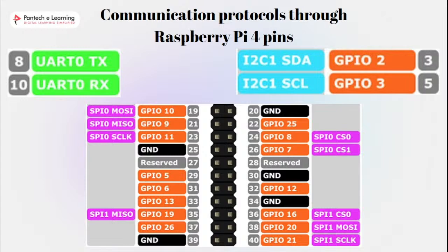For the clock of the I2C, connect all the slaves' serial clock to the serial clock bus. And then data. This is to exchange data between the 2 things, so connect all the slaves' data to the data bus. And as most of the time, you will need to power on the component, you will also need a power pin, which can be 3.3 volt or 5 volt, linked to the VCC pin of the component.